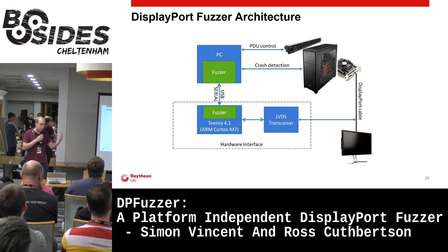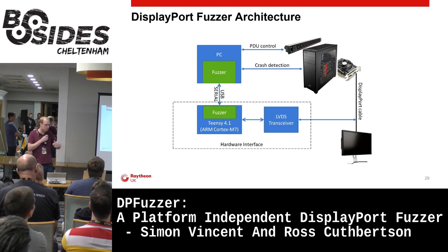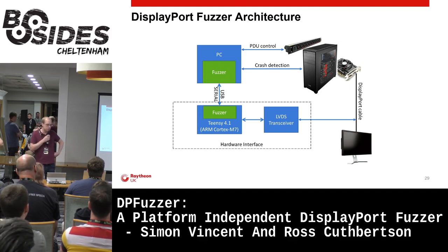This Python fuzzer would then talk via USB to our hardware interface board, our Teensy board, which would then interface directly into the DisplayPort cable, so it can inject data in and receive data via our LVDS transceiver and discrete components.